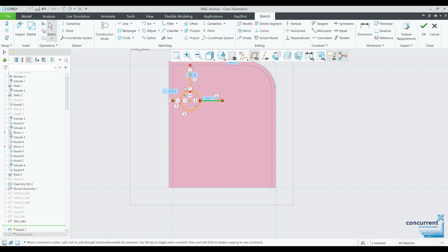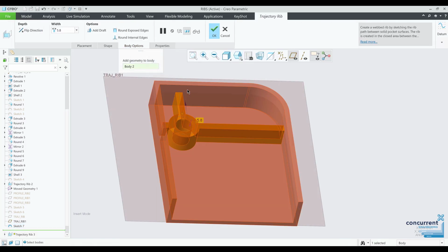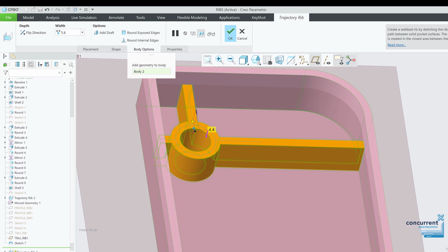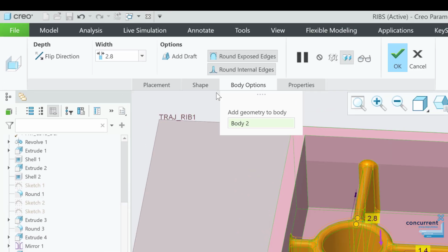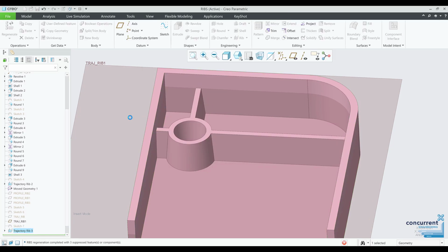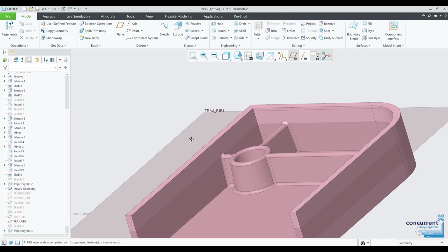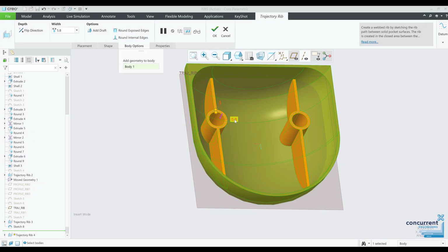You also have further options here specifically useful for creating moulded bosses, gussets and ribs. I can apply taper to the rib, for example, to allow easier release from the mould, and I also have the ability to add internal and external rounds to the top of the rib and also at the base. Really simple and useful. The thickness of the rib can be adjusted, as can be the radius value of the rounds. Your company will probably have some guidelines and policies related to the size of these ribs and rounds, etc.